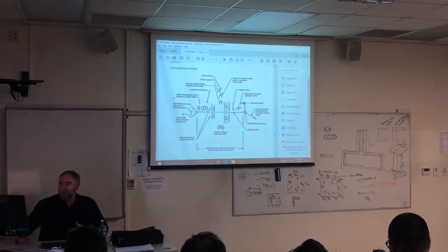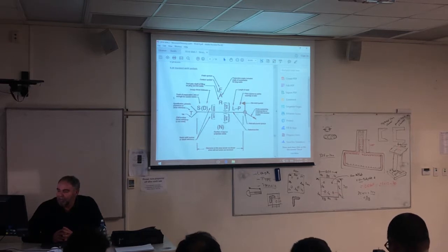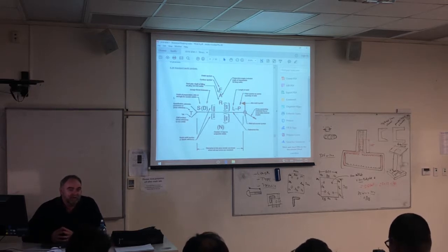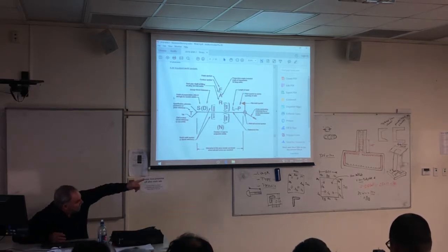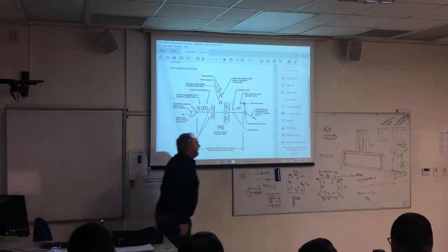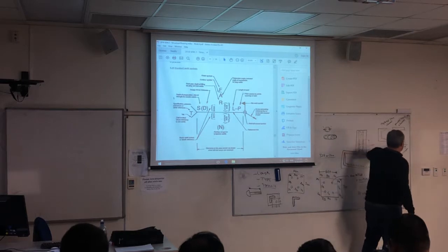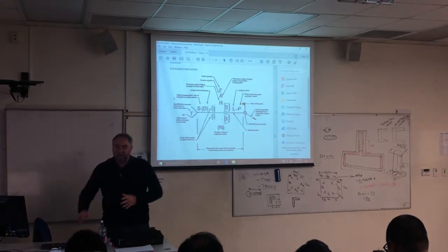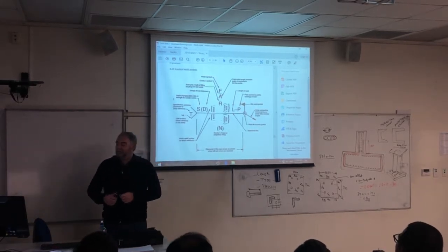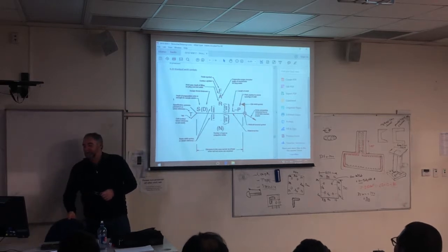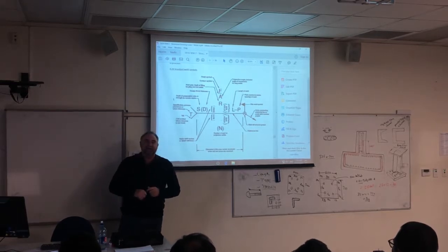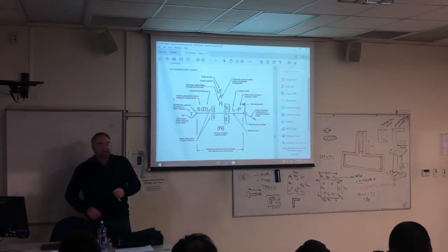Welding. This is how we determine a weld symbol. You are required to do a weld symbol for a 6mm weld, which I've written over there somewhere. 6mm weld. Fillet weld. The next section of notes goes quite deeply into all the different types of welds you can do. I could have been mean, I could have made you do a butt weld. I could have been even meaner and made you do an intermittent MIG weld or something like that. I've stuck to a very common weld and a very common symbol on structural drawing.